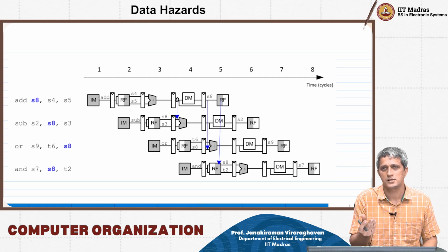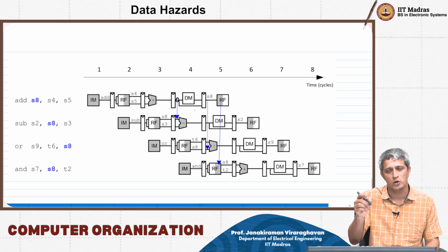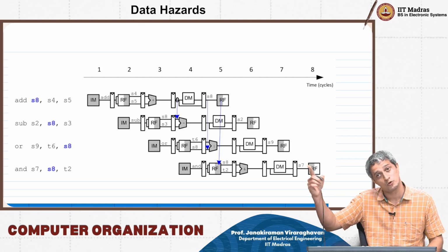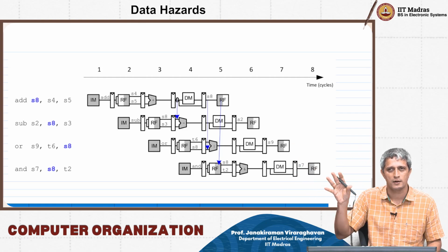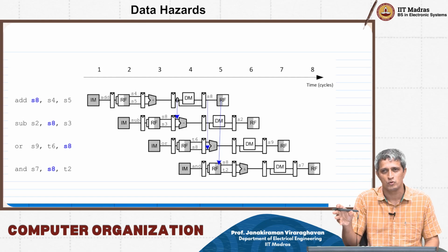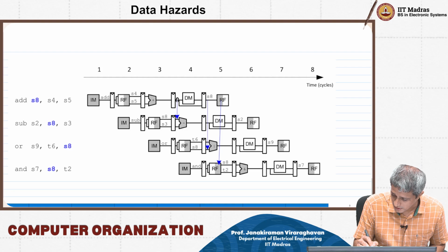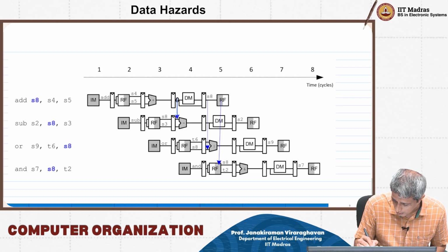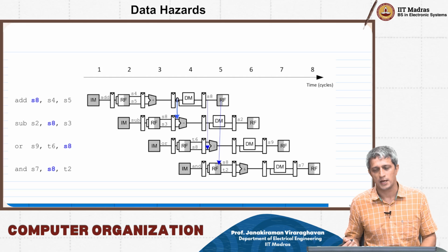It's a 32-bit answer, it's already there. It is exactly the same data which is going to get bypassed through the data memory into that flip-flop, and finally the result W will get written back into the register file. Then why not we simply forward this data to the ALU here? That's all we have to do technically.